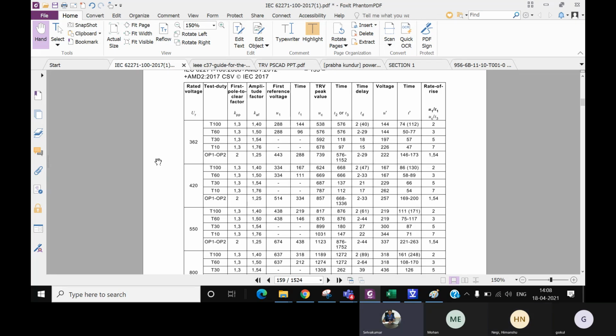The worst-case scenario which was expected has not arrived in real time. But on the other side, I have seen quite a lot of substations where everything is proven: TRV is within the limit, RRRV is within the limit, VFTO is perfectly done, this one is done, etc. But still there is a fault. There are equipment failures, especially the reactors at 400 kV level. Those faults are really severe, despite point-on-wave switching and sophisticated mechanisms.